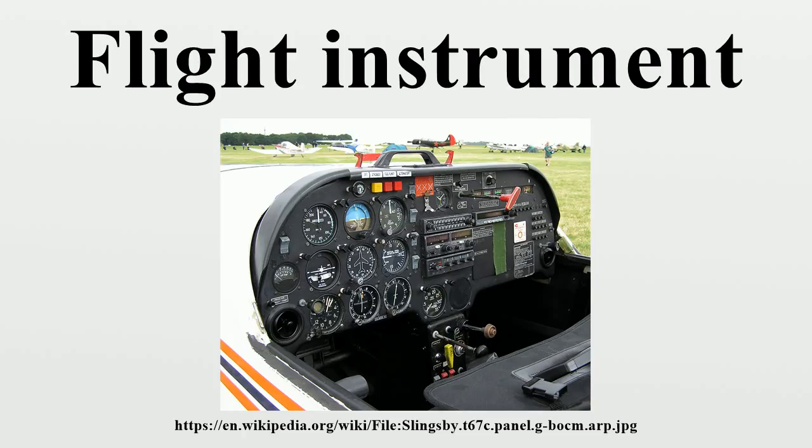In 1937, the British Royal Air Force chose a set of 6 essential flight instruments which would remain the standard panel used for flying in instrument meteorological conditions for the next 20 years. They were altimeter, airspeed indicator, turn and bank indicator, vertical speed indicator, artificial horizon, directional gyro, heading indicator.